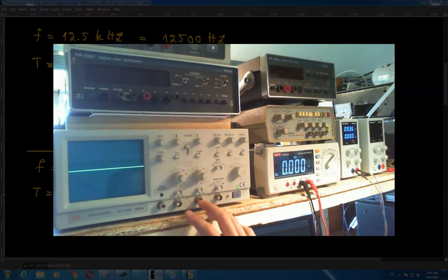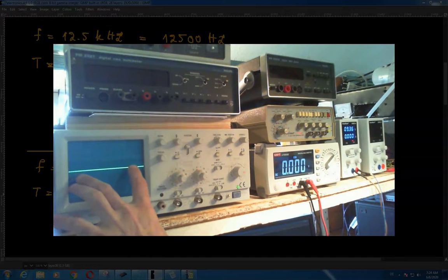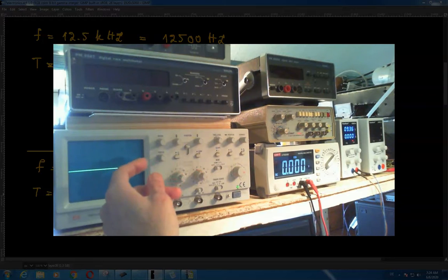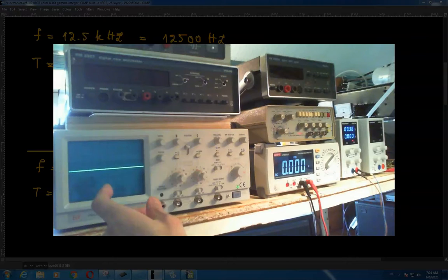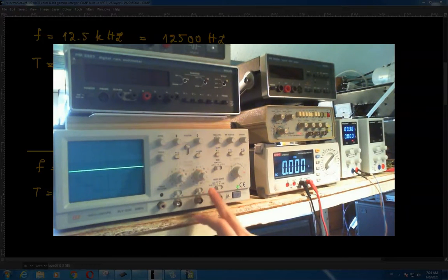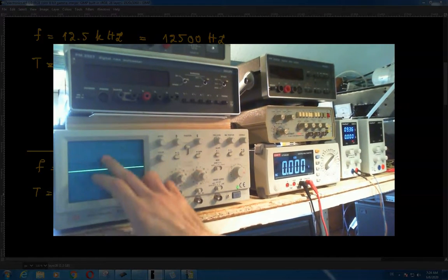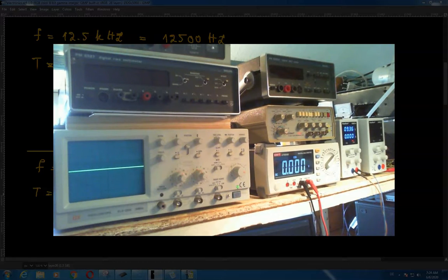So if you want to use both channels simultaneously, the beam that is shot at this screen has to be divided in time, meaning that for some length of time the oscilloscope will be reading from this input, then for some length of time from this input, and it switches back and forth in order to give you two outputs over here simultaneously. And I'll show you what I mean by that.